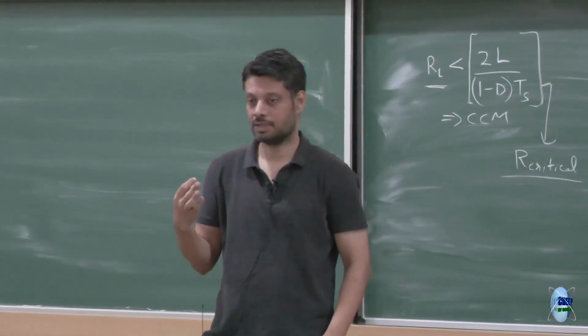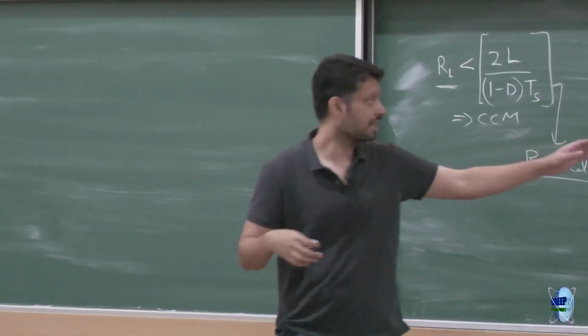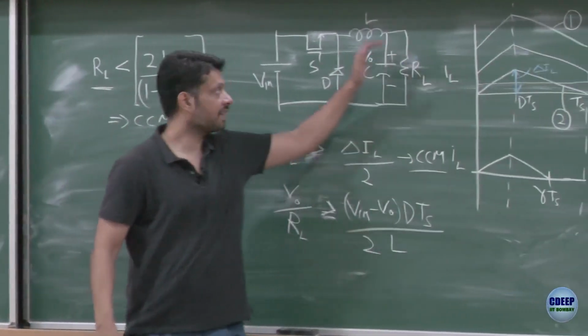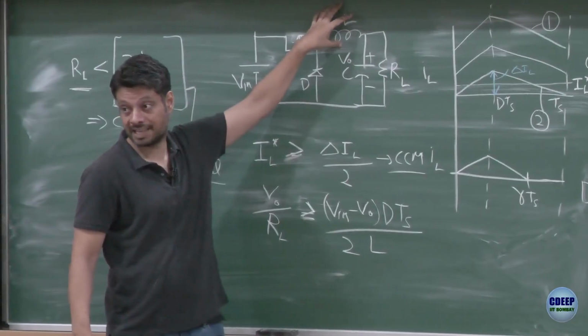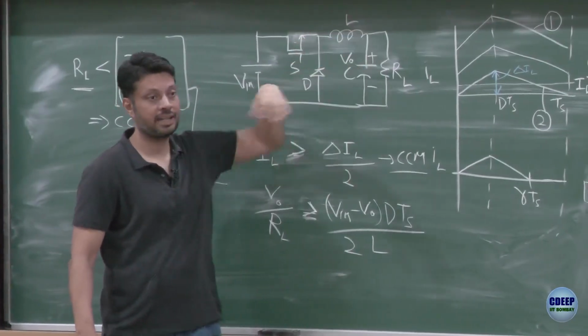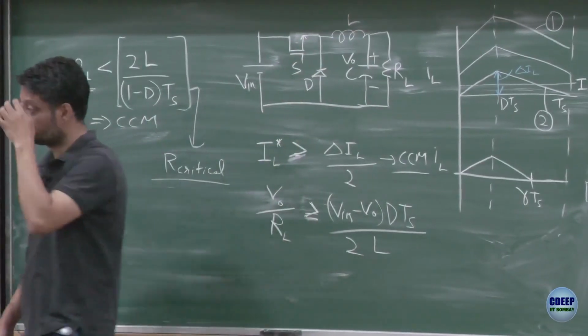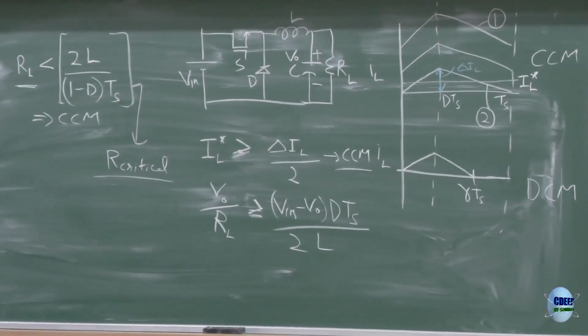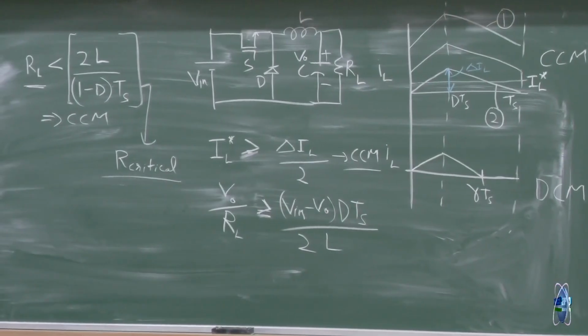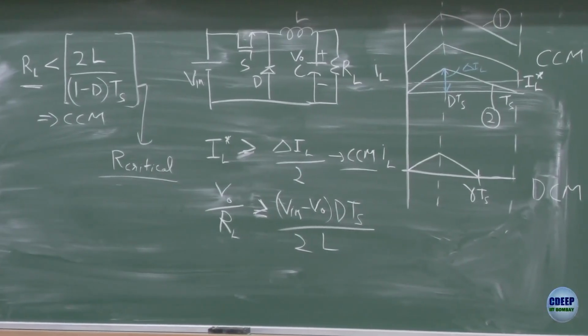It remains the same, right? Because the ripple current is the same, the average current anyways goes from here to here. Since the ripple current component is the same, that's what is flowing here and that's what is leading to the ripple in the voltage. So that remains same, which means the ripple in the output voltage would remain same. Anything else?